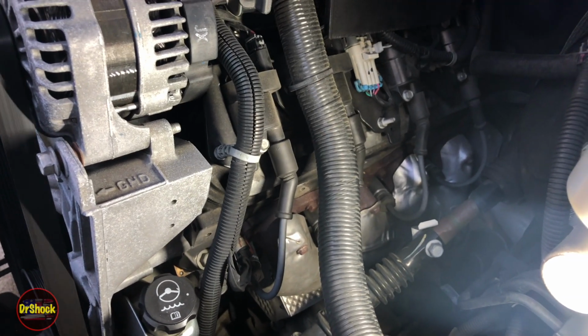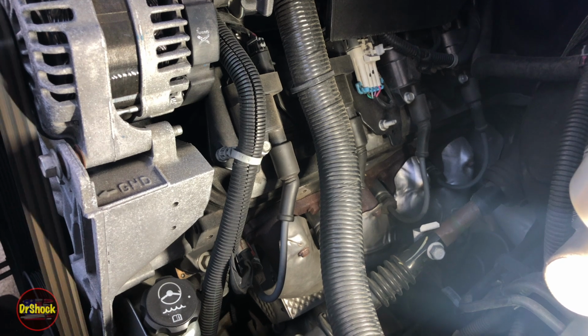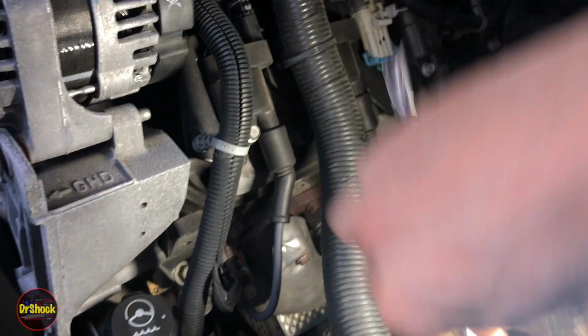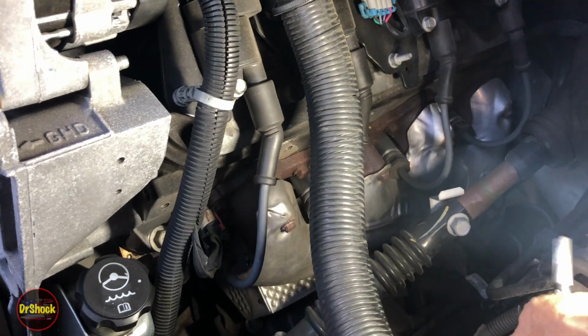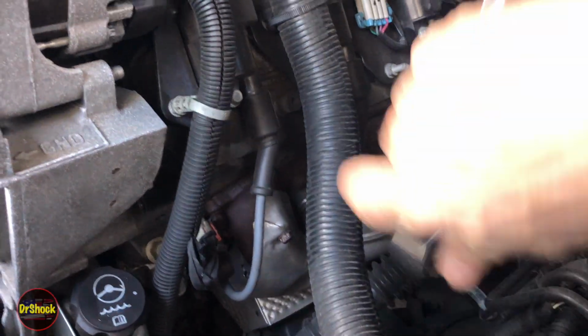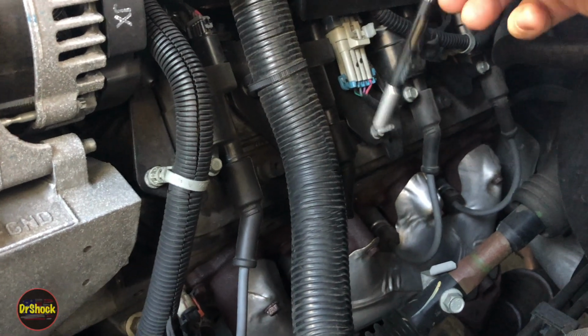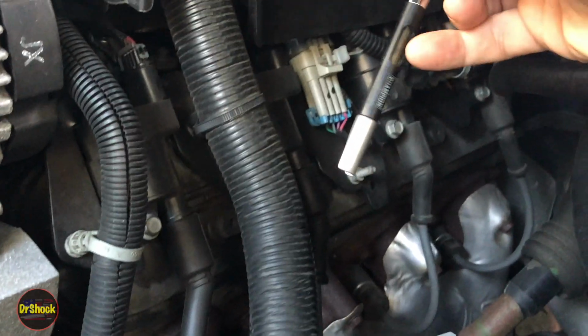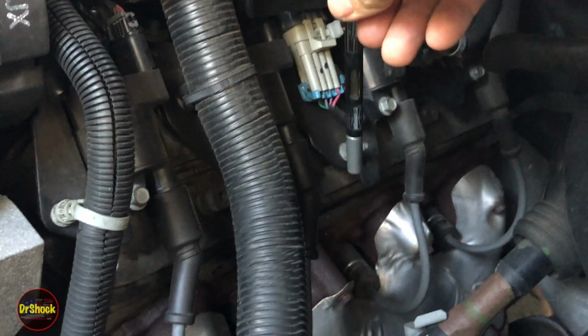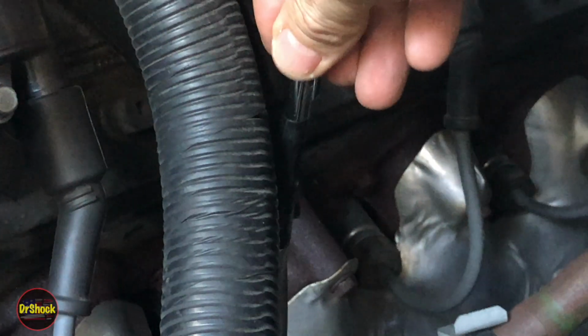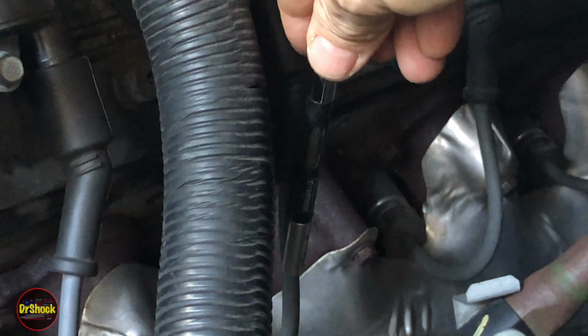So while the engine is still running, I'm just going to use an old school spark plug tester. It's one of these kind of guys. It uses a little tube with a rare gas in it, like xenon or neon, and it'll pick up on the energy going through the plug wire and light up this tube by exciting those electrons. So if we put this on the number 3 plug wire down near the bottom here, you can see this guy flashing, so we know there's energy going from the coil to the spark plug.